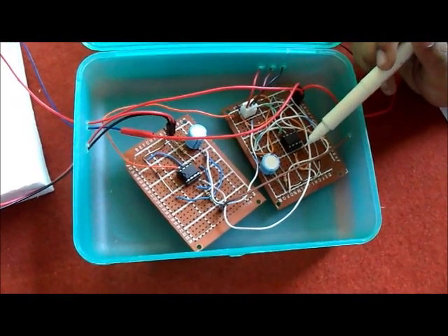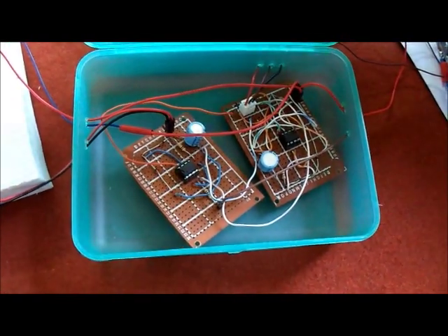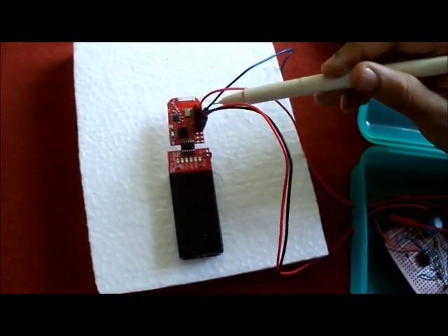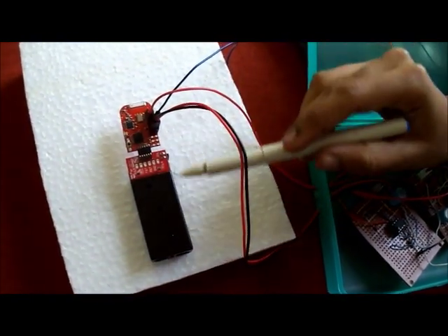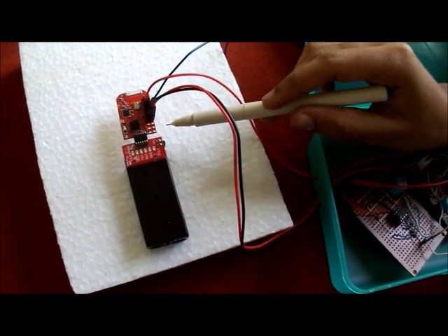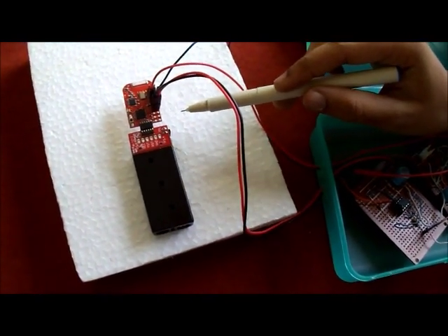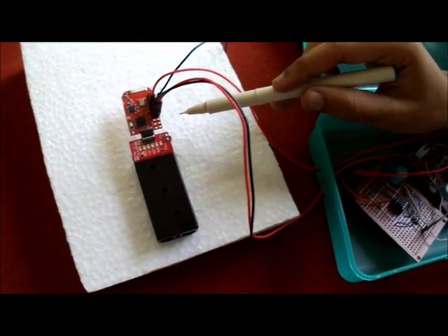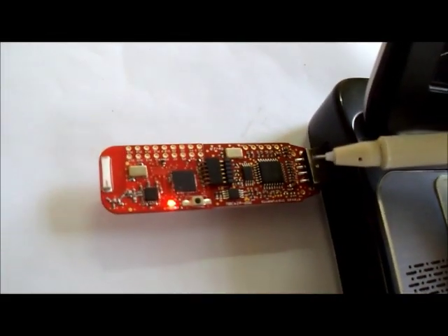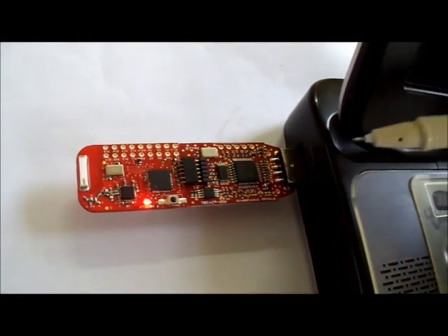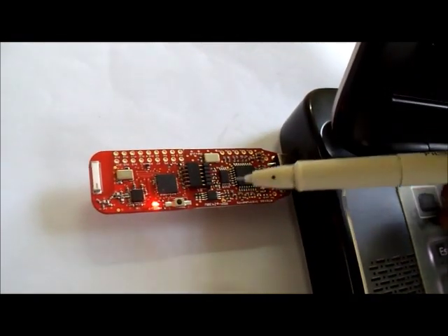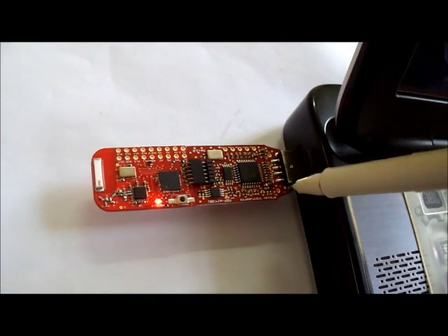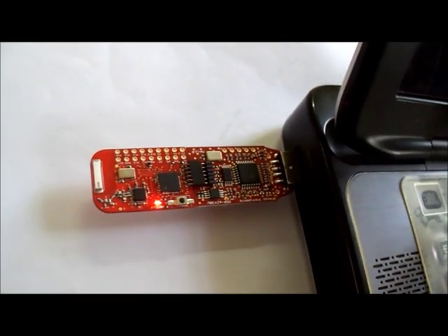Detected peak values are given to the input of the end device of the EZ430-RF2500 kit. The end device is running a program to read analog inputs and convert them into corresponding lamp voltage and current values. These values are transmitted using the TI network protocol. The access point connected to the PC is running a program to receive data using the TI network protocol and send it to the serial port of the PC. The received data through the COM port is read and displayed.